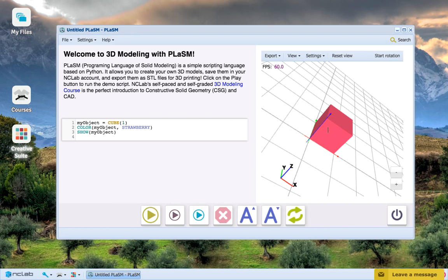So, to sum up our lesson on spheres and cubes, the simplest shapes to build in 3 dimensions, remember a few things. Remember that they are both functions which take one parameter, defining the radius of the sphere and the side length of the cube. Remember that spheres are centered on the origin of the system of coordinates, and that cube is made in the first octant with one vertex on the origin and edges along the positive axes. Lastly, remember that spheres are expensive objects to build in terms of computing time and resources, so they may take more time to create.